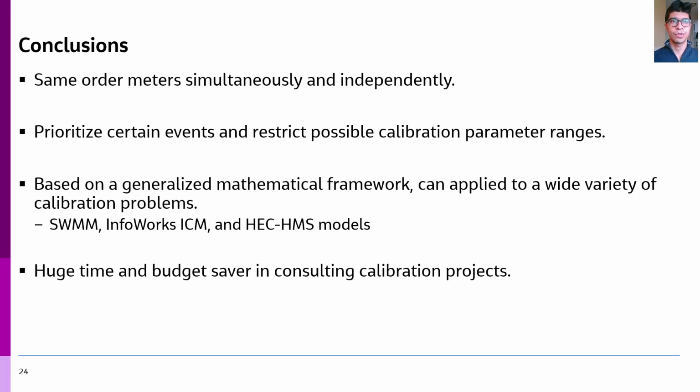We want to make sure that we're going to collect the data long enough, 2 months, 3 months. In this case, we flow monitored for 3 months to be able to capture some of the extreme events, being dry, and being wet as a result of any sort of rainfall, so that we can calibrate for those extreme events.